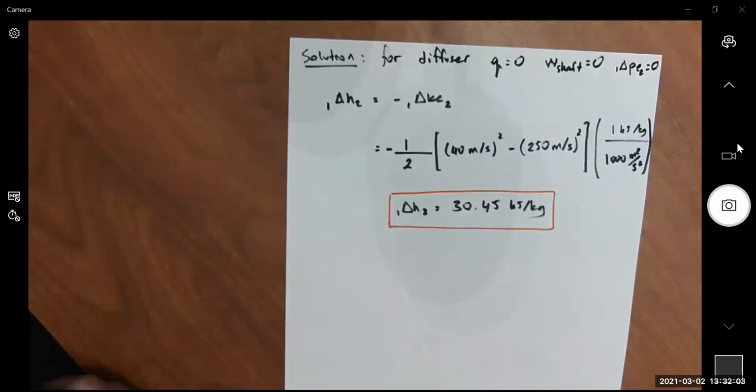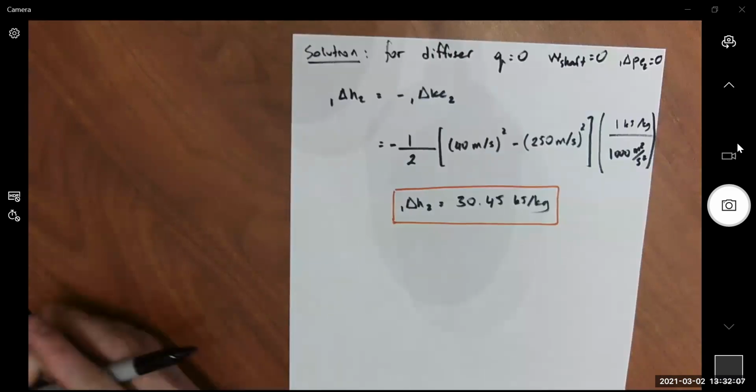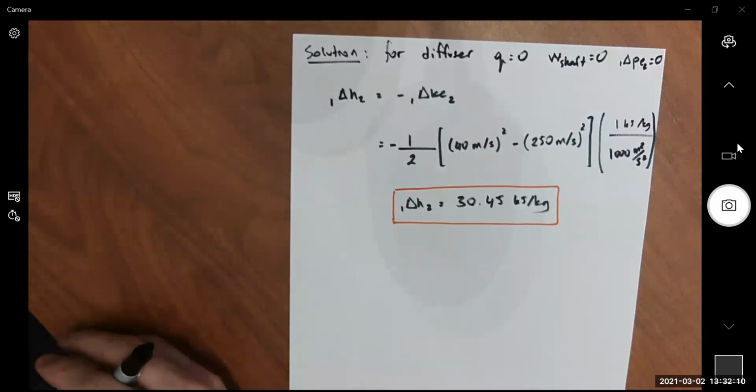Okay. There's a little bit of a trick here. Listen carefully. I just found my enthalpy difference between state 1 and state 2. And since I'm going to use a constant specific heat model, which is CP in this case, if you go ahead and check your tables for an ideal gas air table, what you will see is CP doesn't change dramatically as a function of temperature. It is around 1.04, 1.05 with a couple hundred degrees temperature increase or decrease. The change in the CP or CV is really small, if you check your table.